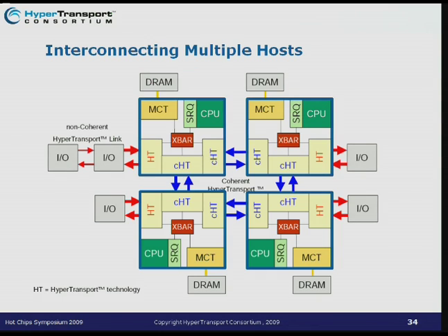We will need to define some HyperTransport links as coherent links, while other links are defined as non-coherent links, so as to distinguish between links that are used for implementing the cache coherence protocol, and therefore communicate one core with another, and requests from a core here to some memory controller in a remote device, and distinguish them from requests that go to some I/O devices.